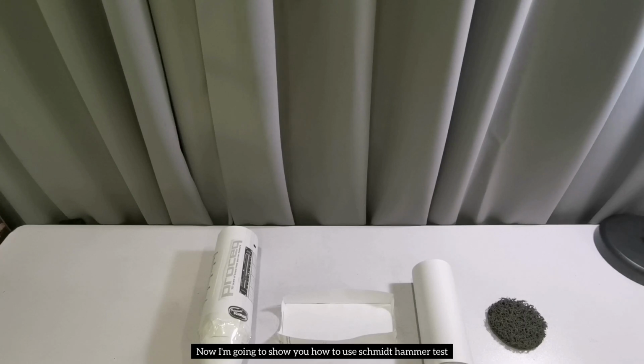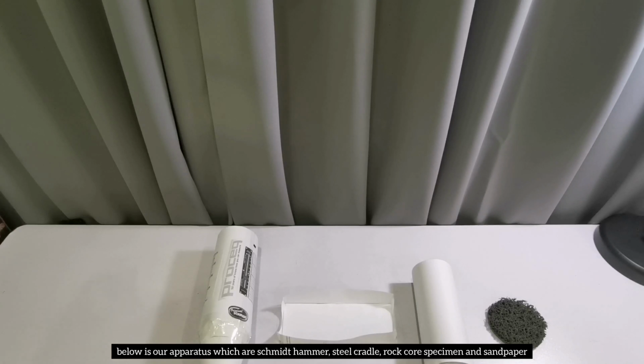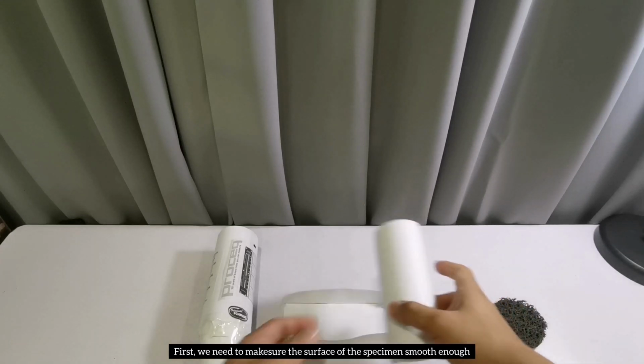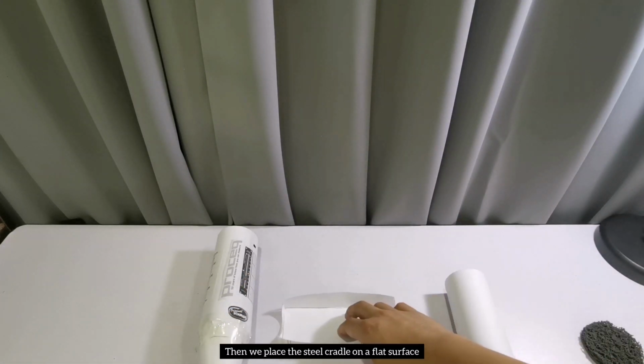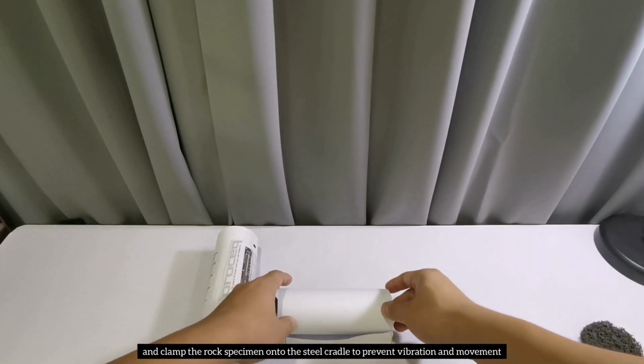Now I'm going to show you how to use the Schmidt hammer test to determine the compressive strength. Below is our apparatus, which are the Schmidt hammer, steel cradle, rock core sample, and the sandpaper. First, we need to make the surface of the rock specimen smooth enough and clean by using the sandpaper. Then we place the steel cradle on the flat surface and clamp the rock specimen onto the steel cradle to